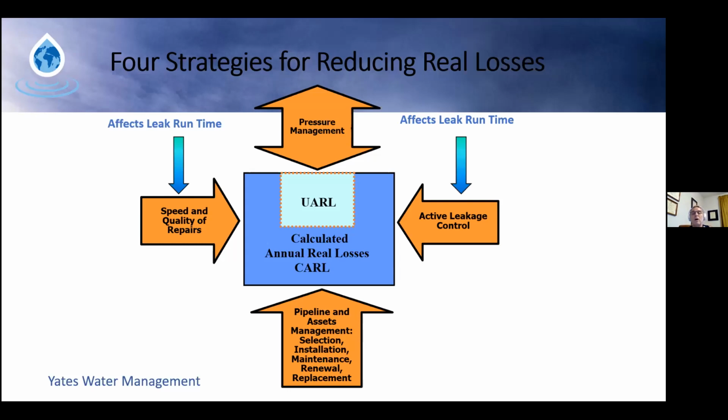Up above, also want to point out, however, the methodology called pressure management, and I'm sure many of you are using this today, which also will provide better service to your customers, but certainly minimize your losses. And it's the only one that shows that things can go two ways with pressure management. You can have more leakage if you've got more pressure, or you can have less leakage if you have lower pressure. And that's what that double arrow is meant to reflect.